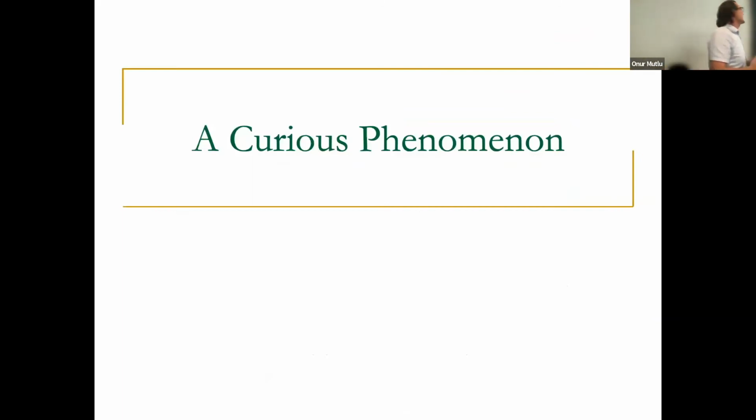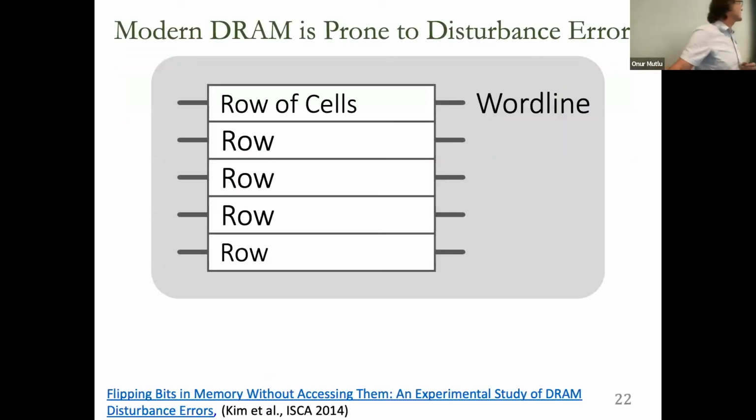So while we were doing these studies, we were actually doing a lot of studies with flash memory as well. I'm going to show you a picture of infrastructure with flash memory. And in flash memory, there are a lot of errors. One of the issues was read disturbance errors. Together with Intel, we wanted to analyze the read disturbance errors in DRAM as well.